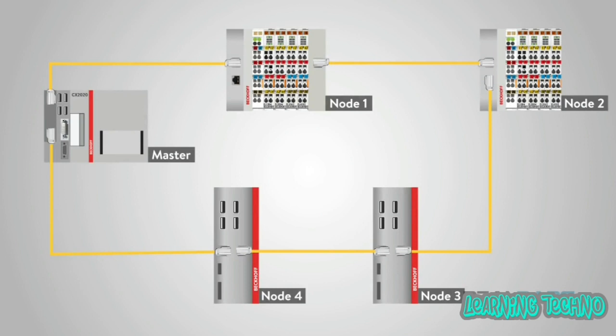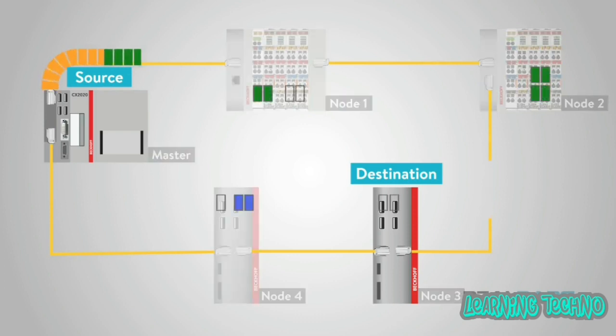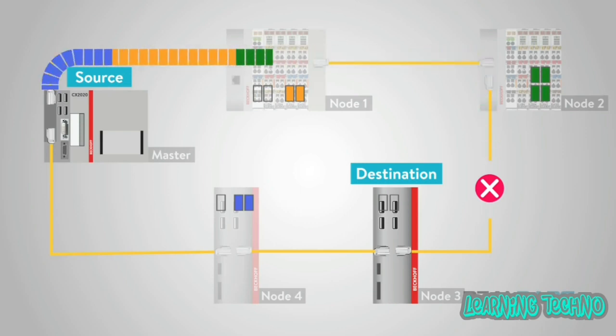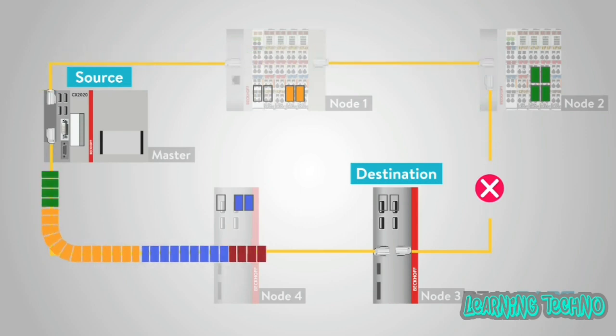Considering the inherent ring technology of EtherCAT, connecting the network in a ring topology would be a redundant system, if you can imagine. Because it's inherently a ring topology, connecting the master's second port, if available, would provide redundancy on the other side of a network break. Each topology type should be investigated for your network to conclude which solution would be best for your application.